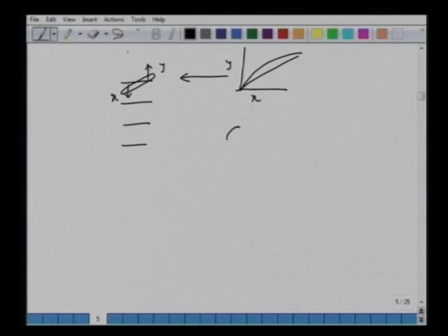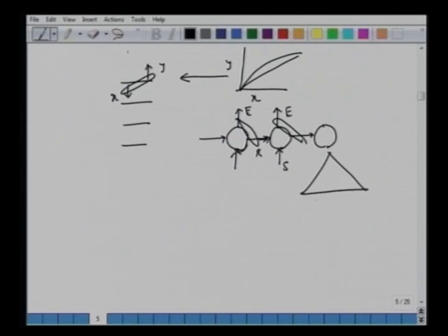When we talked of extraction, then we say that well, we have cascades. So one is streams, another is streams, give them equilibrium, they leave in equilibrium. So here also you bring this constant raffinate in case of extraction, treat with the solvent, we have extract here. The two leaving streams are in equilibrium, and these two leaving streams one can mark on this equilateral phase diagram as tie lines. So here we have y and here we have x. So we are talking of equilibrium approach or a stage wise approach applied to stage wise operation.